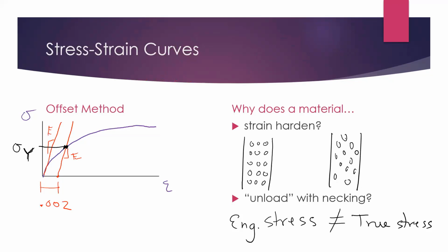That would be the Young's modulus, right? The slope. Yes. Is that subscript capital Y? Yes. Yeah. Other questions? So this offset method is just deciding the sigma y. Yes. This offset method is to get your yield stress when it's not visually apparent.